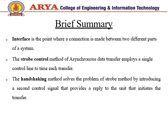This is a brief summary. Interface is the point where a connection is made between two different parts of the system. This topic is completed in lecture number 1. The strobe control method of asynchronous data transfer employs a single control line to time each transfer. The handshaking method solves the problem of the strobe method by introducing a second control signal that provides a reply to the unit that initiates the transfer.